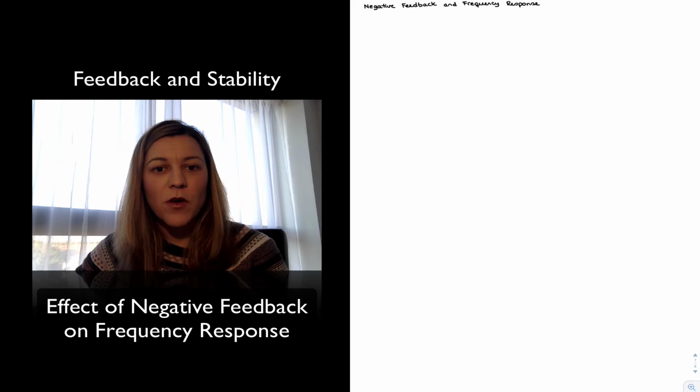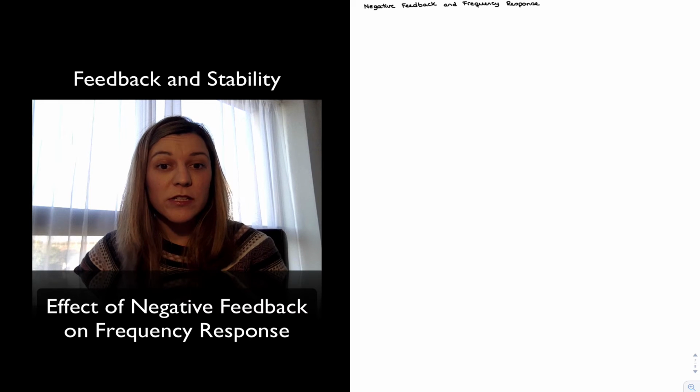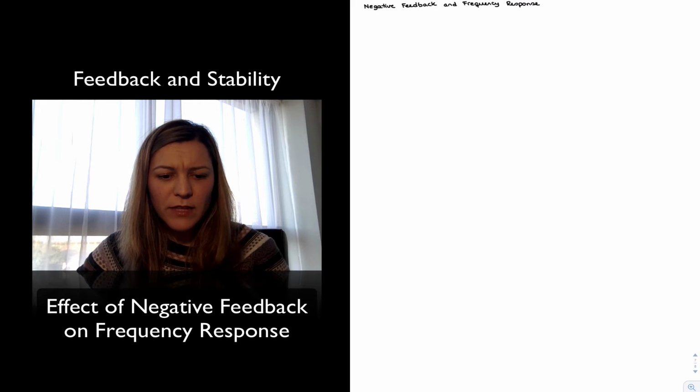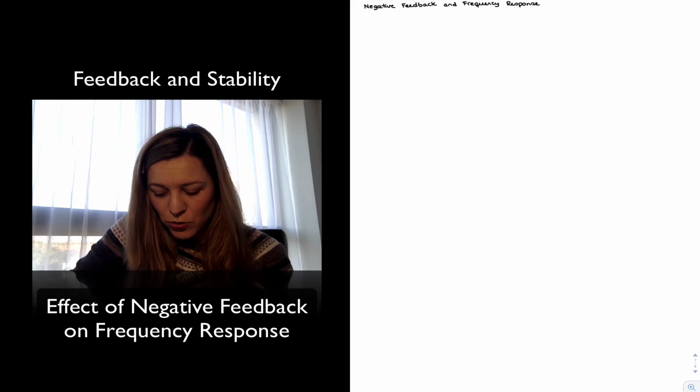of the system. We have also seen that it increases or decreases input resistance and output resistance by the same amount, the amount of feedback, depending on the type of feedback configuration that we have. And so we have seen that negative feedback has all these great benefits at the expense of gain. And so our generic design strategy for our voltage amplifiers, in this case, is going to be the following.